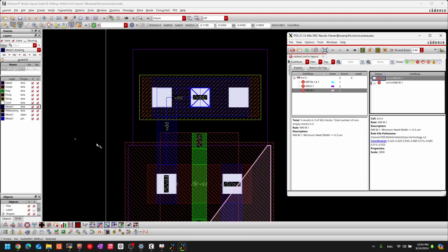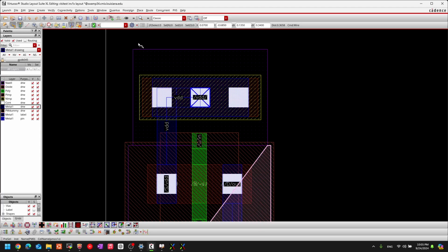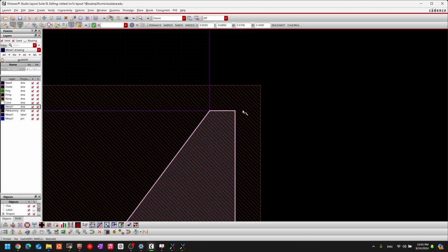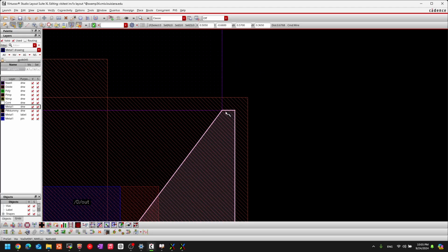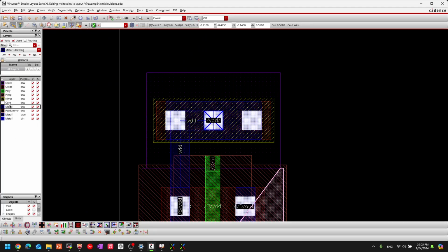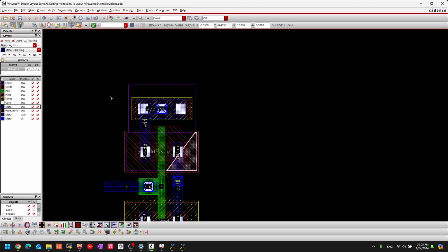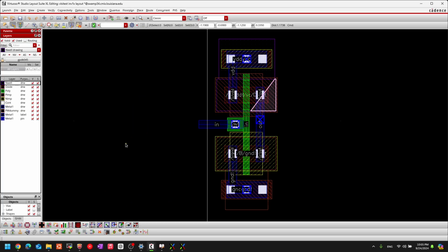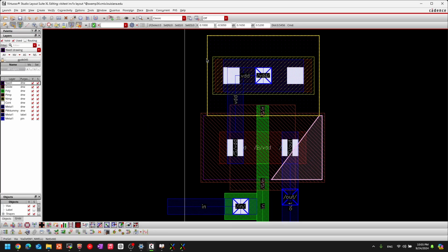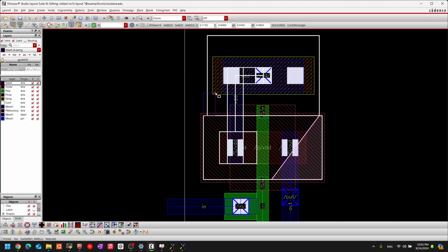A solution to this would be creating a rectangle that would enclose both of these, or maybe have an equal edge rather than having these small edges on the corner of this end wall. So let's do this. We'll have to look for the layer. This is the end wall layer. All right, so I got the end wall layer, and I pressed R for rectangle.